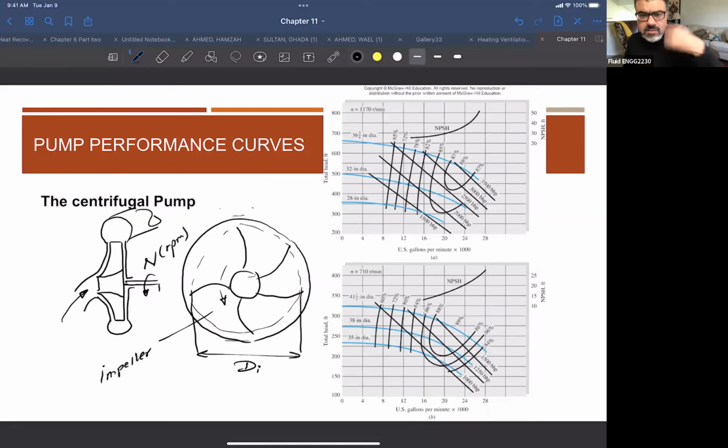So if you increase the speed of the impeller, you might change the performance of the pump, and then you can basically achieve higher heads for maybe higher RPM or higher rotational speeds. Same thing if you are changing the impeller diameter, of course, to a certain limit. So within certain variations, right? So the casing that is designed by this manufacturer will accommodate plus or minus some different impeller diameter.